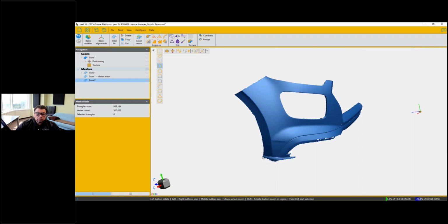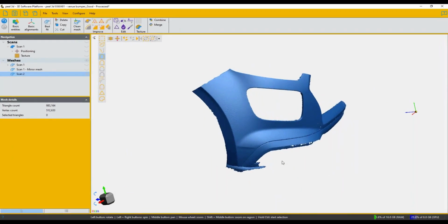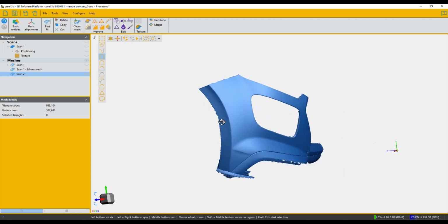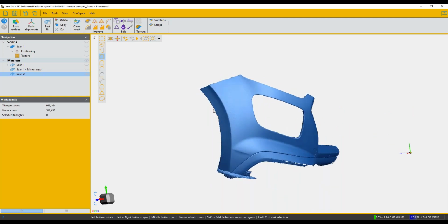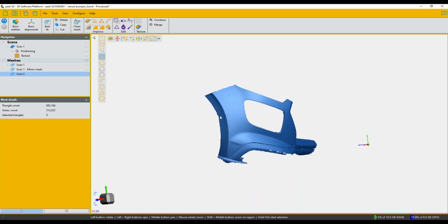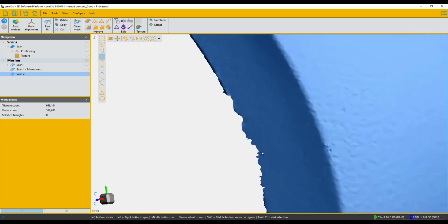So we would repeat this process. We'd continue selecting all the triangles along the perimeter that we no longer need until we only have the main body of the mesh that we're looking for. Once we've done that, we can then start to process and condition the boundary of the mesh. We can fix it up to smooth it out. We want to make sure that we have a very smooth boundary. If we were to try and flatten something like this, then our pattern would have this characteristic there, so we want to smooth this out.